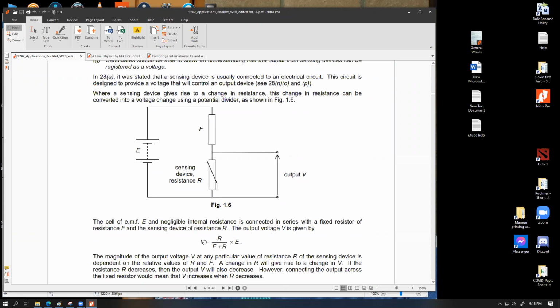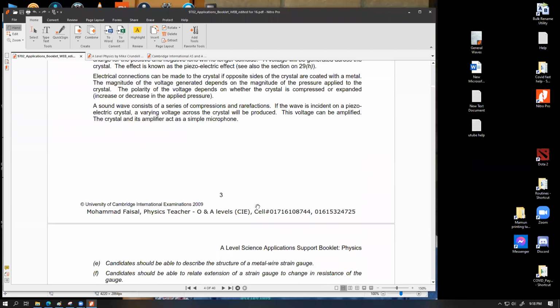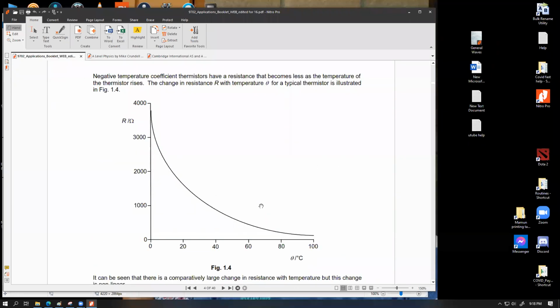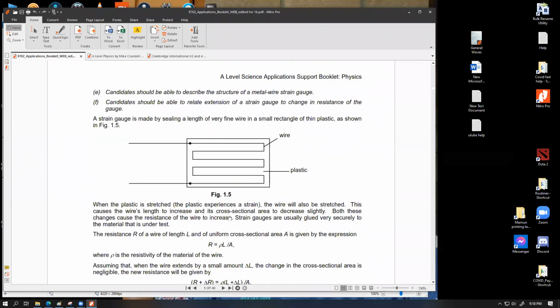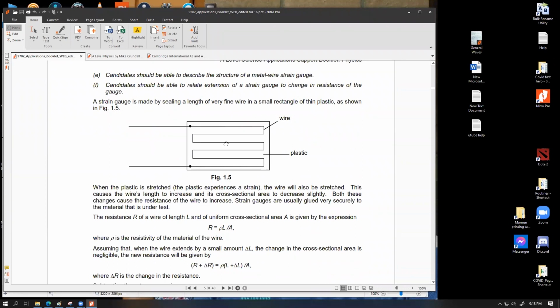And if we can measure this voltage properly, then we can actually have a measurement of the resistance. And if we can feed the resistance versus temperature data within the brain of that machine, we can also convert any measurement of resistance into the relevant measurement of temperature as well. And the device might as well work as a thermometer, a precise thermometer, if you ask me. So that's one way to deal with it.